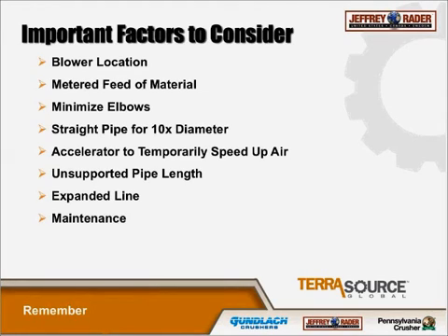Maintenance is very important. Extend the service life. If you have any kind of leak or hole, you want to make sure that you fix it properly. Scab patching is just not going to work because it's really just going to make the system get worse and worse. And if you want that system to run at full capacity, full efficiency, you want to inspect and make sure that everything is not worn. A lot of mills will rotate the pipes even to extend the wear life of their pneumatic system.